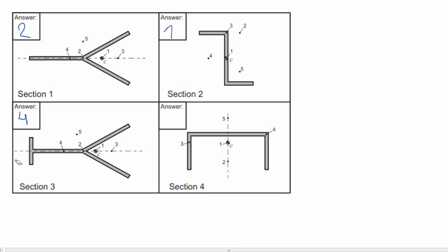Now, section 4 is a C-section on its side, which we all know very well by now. We know that the shear center is for sure on the vertical symmetry axis. And then, because in the case of a horizontal shear force the shear flows in both vertical members will be in opposite directions, we know that the shear center will be in point 5.